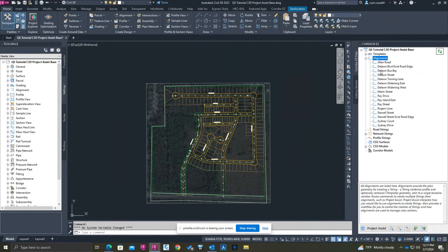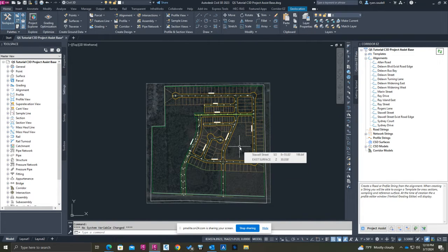We've also got alignments. These alignments that you see on the right side, when you install the package, you'll have access to those civil 3D alignments. And as I hover around, you can see it highlight them in the plan view. But right off the start, if I've got my alignments set up the way that they need to be, I've got a civil 3D surface, and again, just to reemphasize, this is a civil 3D alignment.